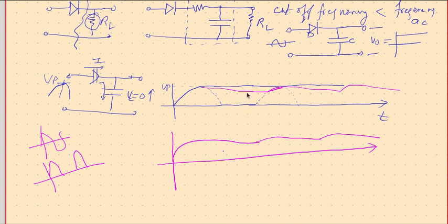But before getting into the regulator, there is another option. If we take the missing negative cycle and convert it into a positive cycle, then our situation would be better, because the discharge path is almost half a cycle, and if you can add the negative cycle as a positive cycle here somehow, then the discharge time will be very small. Therefore, the amount of charge discharged will be very small, and hence this looks even better than that.